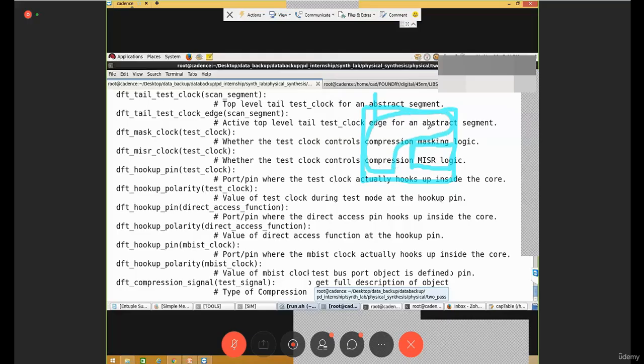So in the logical synthesis stage, the tool will not assume the area constraint. It will just randomize and convert the gates according to a random amount of area. Now, when you do physical implementation, you are providing the physical information of where the pins are placed, the location of the memories, and the vacant area.